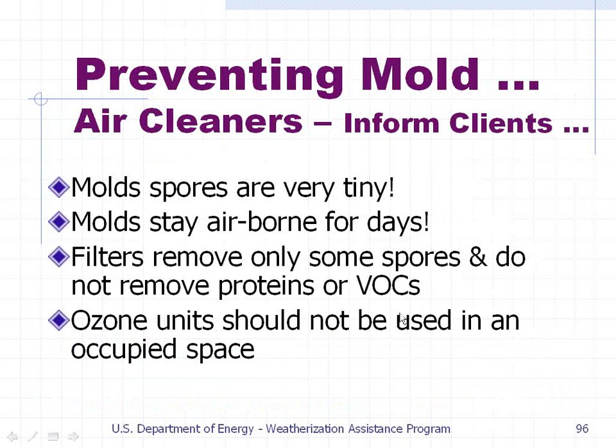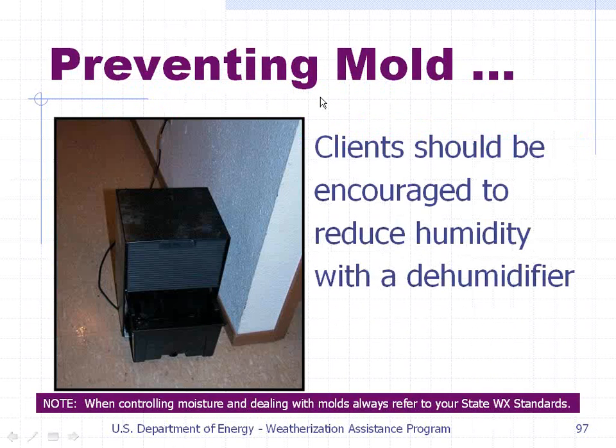Now, preventing mold through air cleaners. Inform clients, mold spores are very tiny. Molds can stay airborne for days. Filters remove only some spores and do not remove proteins or VOCs. Ozone units should not be used in an occupied space. Preventing mold, clients should be encouraged to reduce humidity with a dehumidifier.